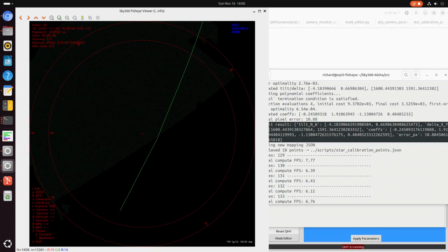So basically, the object detection is going to produce an object list, and that is going to be fed to a tracker, and the tracker is going to track its position and send the position to the PTF, so that we collect an image from each one of the objects.